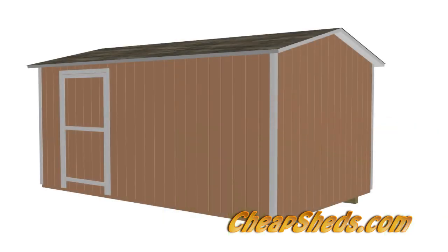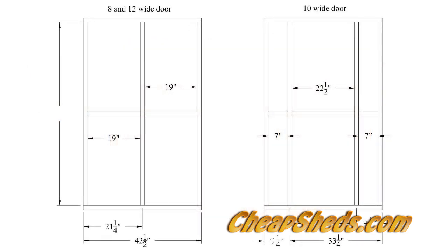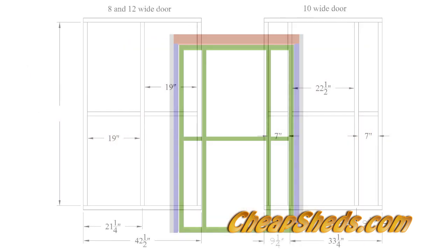You can also place the door anywhere on the wall you like. However, I recommend that you place it on some increment of 12 inches from the corner. This way your stud spacing will be covered by figure 5B. Otherwise, you might have to add an additional vertical upright if the siding breaks where there is no stud in the inner door frame.